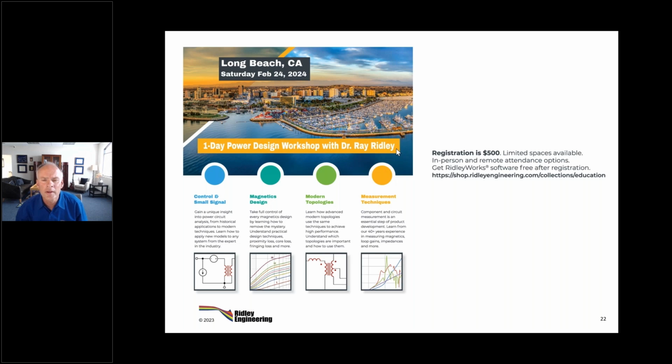The blue line, somebody's talking about the DC losses in the charts. Is it measured with a digital multimeter? Well, we do it with that, but we also do it with a frequency response analyzer because we're accurate down to below 1 milliohm with that, and we can calibrate even better than that. But yeah, DCR is fine for that.